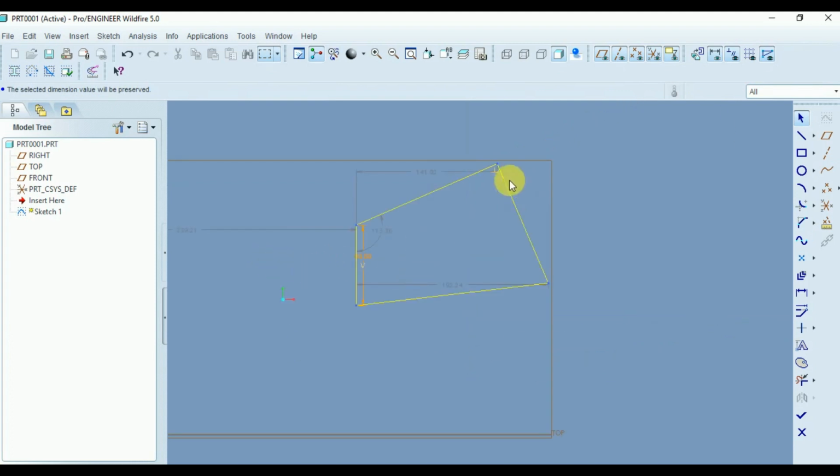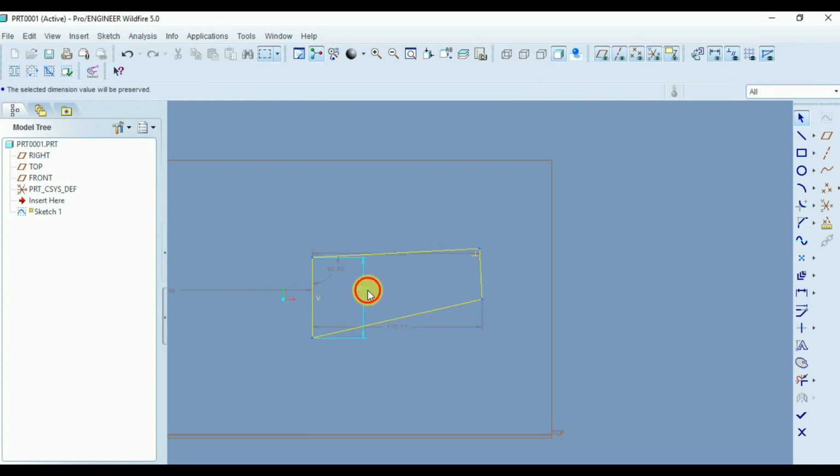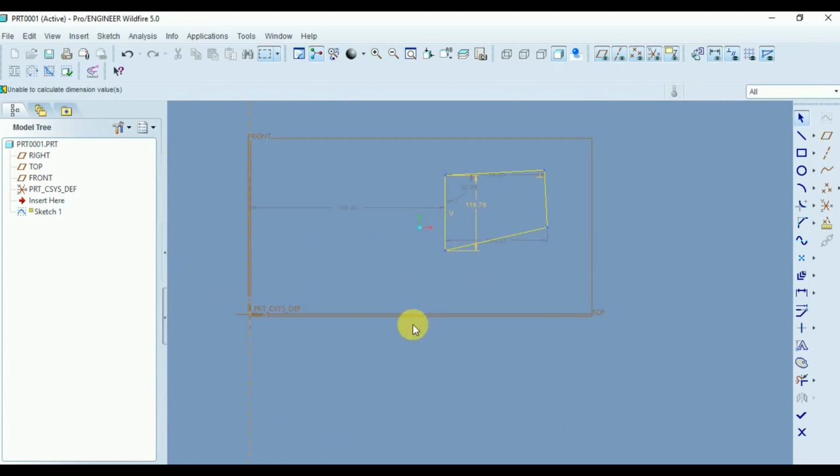Now as you can see, I can move this line, but it will not change because this line is locked. It will always stay in a vertical position, and you cannot shorten or elongate it. You can adjust the other lines, but you cannot adjust this line because it is locked now. By doing the same, select it, hold your right click and unlock it. Now you can change it also. You can see I can shorten it and enlarge it. So this was the use of this tool.